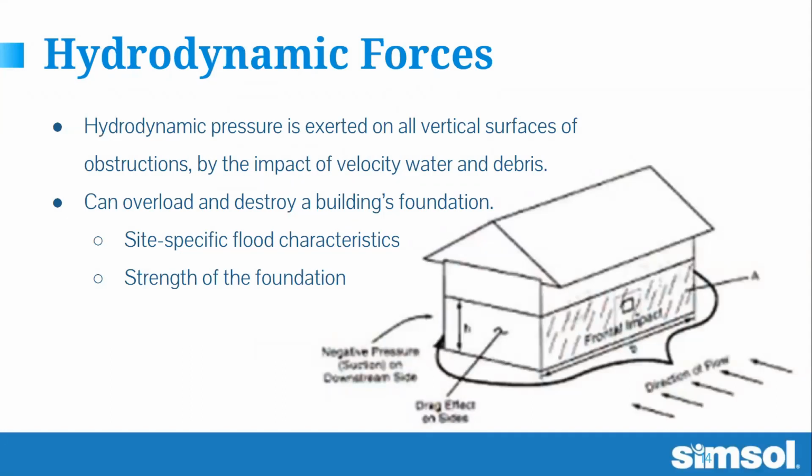So with hydrodynamic forces, we have moving water, the dynamic portion. The water moves very much like air. If you're familiar with wind impacting a structure where it pushes on one side and pulls on the other as it goes by, water does exactly the same thing. However, because water also brings with it a lot of debris that can impact the building, and water is so dense, the water pounding on the side of the building alone can cause damage and destroy a foundation. You're going to have to look for the site-specific characteristics and the strength of the foundation. Obviously, an older foundation in deteriorated condition is not going to be as strong as a relatively new one, particularly with the new building codes that have been enforced recently.